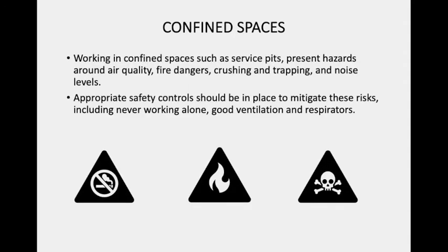Confined spaces. Working in confined spaces such as service pits present hazards around air quality, fire dangers, crushing and trapping, and noise levels. Appropriate safe controls should be in place to mitigate these risks, including never working alone, good ventilation and respirators.